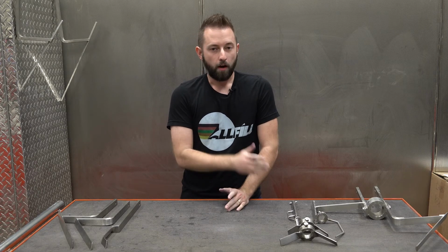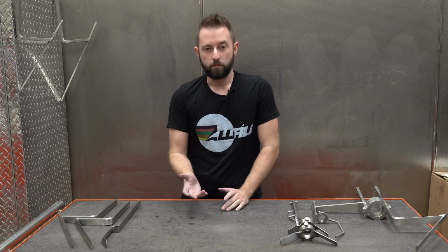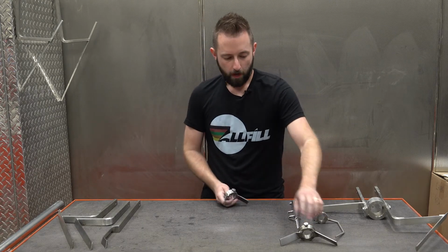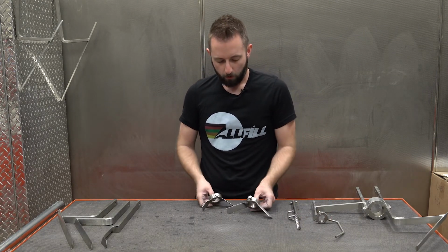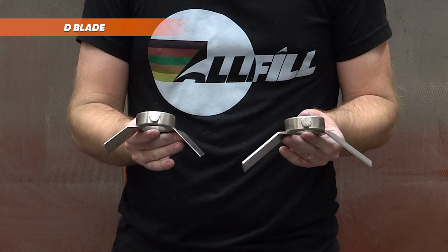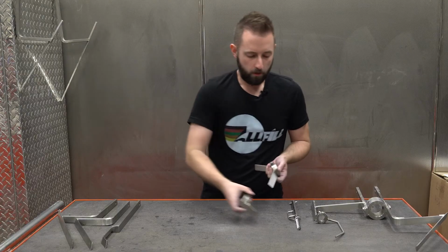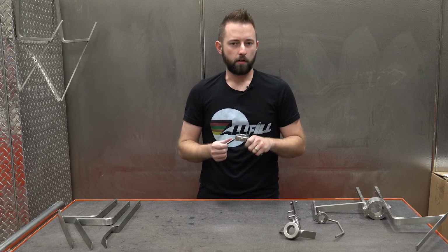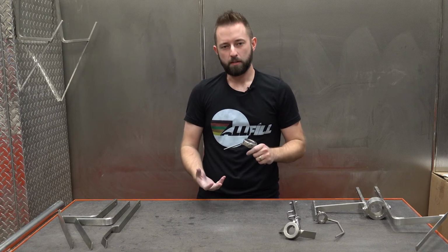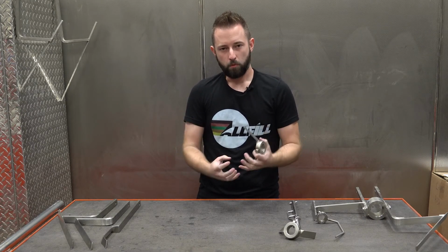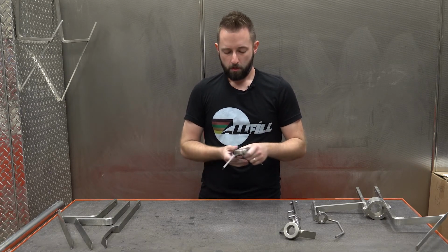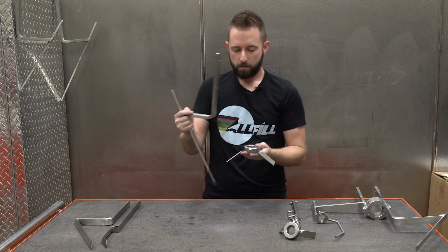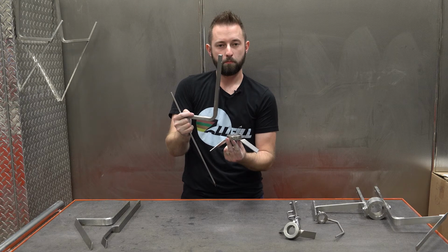Now we also offer high speed agitation blades, and there's a couple different configurations for that we'll go through right now. We have our standard high speed agitation, which is what we call a D blade. They come in 2 different sizes, a small and a large. Typically we'll use a large, and these are for wildly non-free flowing products, things with an oil content, a fat content, that really don't like to move without force. So we'll usually marry up one of our slow speed blades and a high speed D blade.